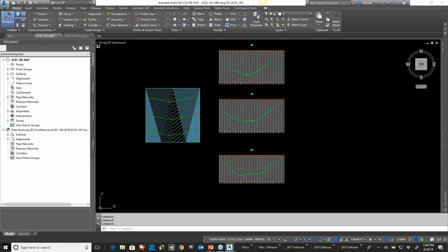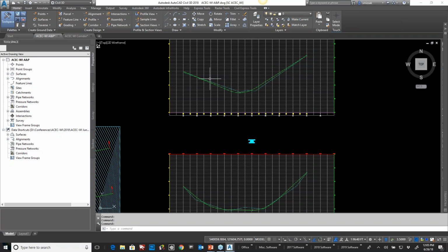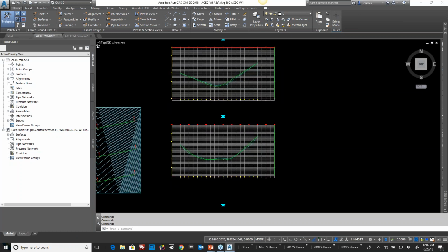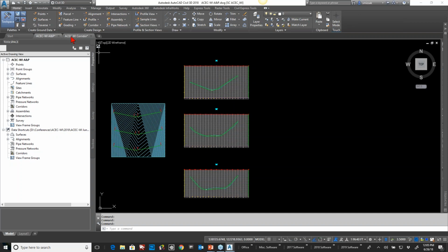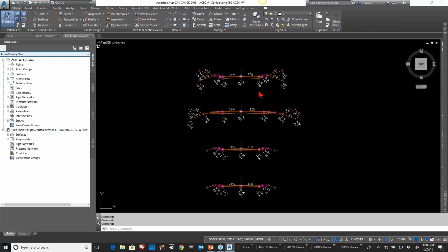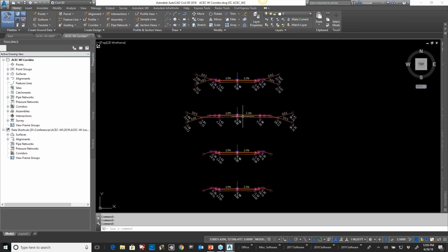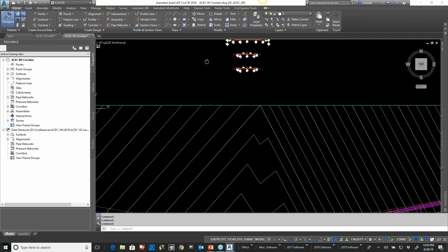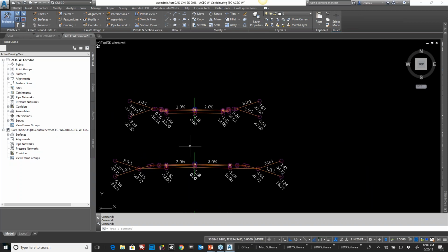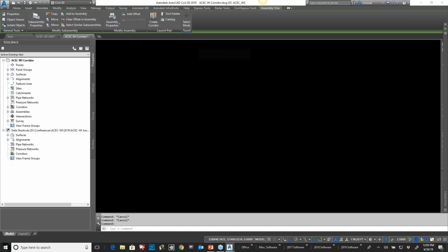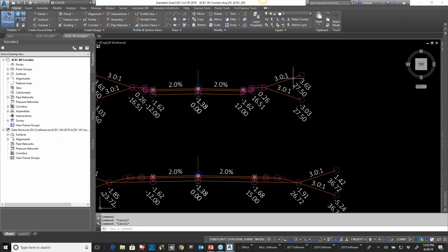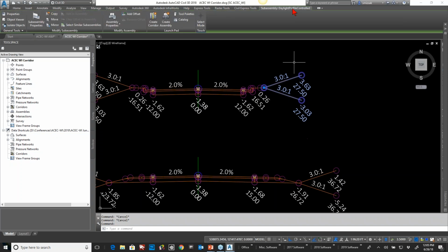And what I've done is I built a fake surface in here. It's got some relief in there, and built a proposed profile 1, 2, and 3. And then I came through and built a corridor 1, 2, and 3. One being with the daylight, one with the cut fill, and one with the link slope. Well, the one I really want to look at is the daylight one. So I'm going to quickly click on there, and it's saying it's assembly 1. And this subassembly is the DaylightProfileControlled.